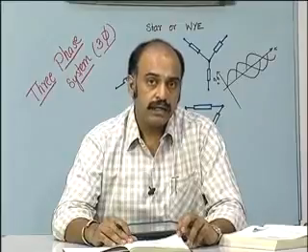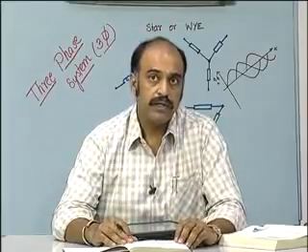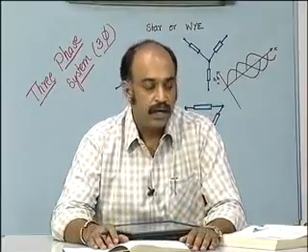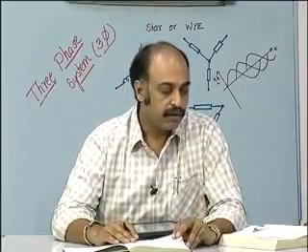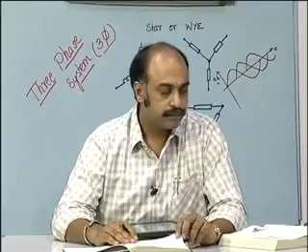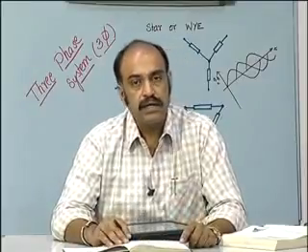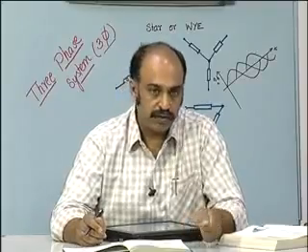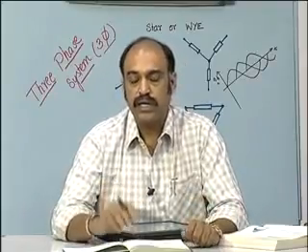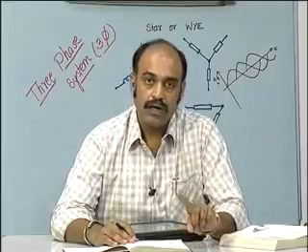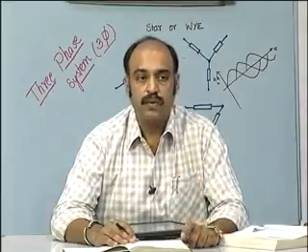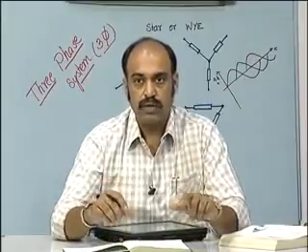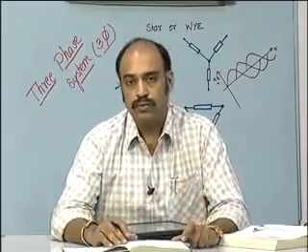In case the power factor is very low, less than 0.5, one of the watt meters can show a negative value, in which case, if it is a single direction watt meter, we must reverse the switch such that you can see the negative direction power flow, or you use a center zero watt meter, in which case you take the negative value, convert it into an absolute value, and then add up the two powers.